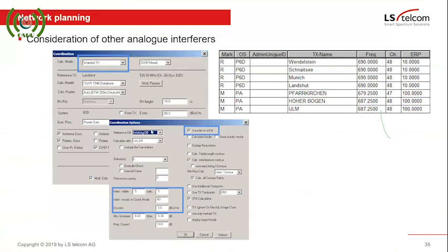Okay, so yes, we've talked about a single frequency network, but obviously there's always also the potential of analog interference. So what you will typically do in a scenario where you've got a single frequency network with a specific type of transmission, maybe DVB-T2, and you've got your analog signals, is create C over I, coverage over interference, scenarios.